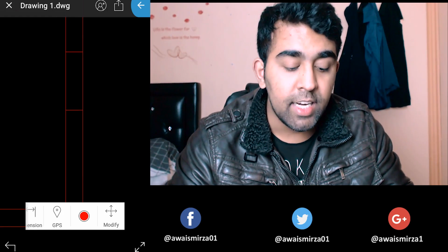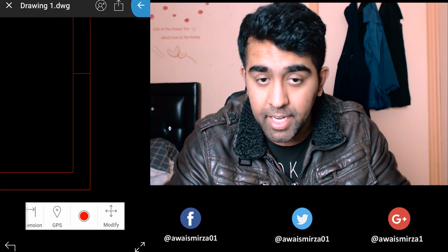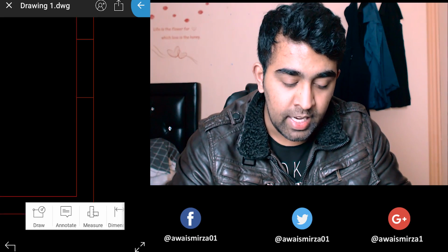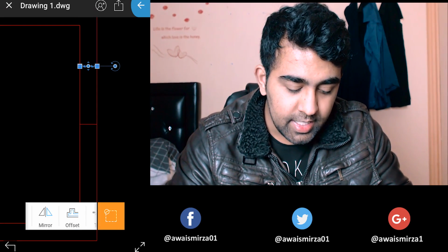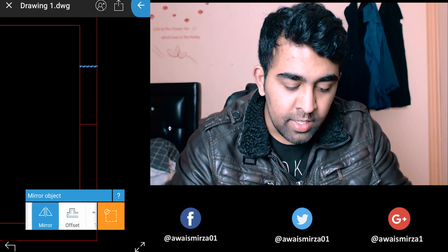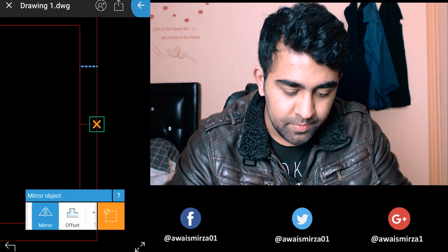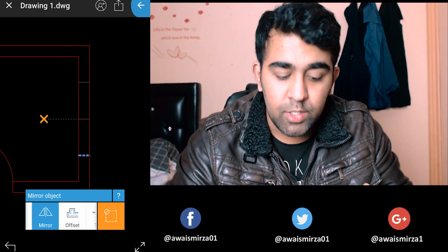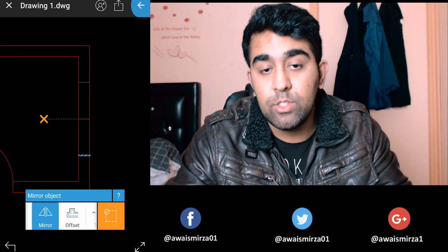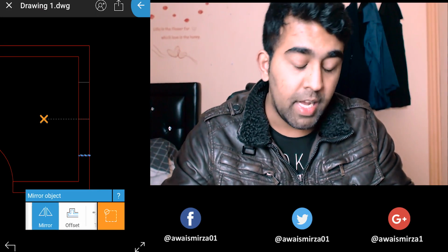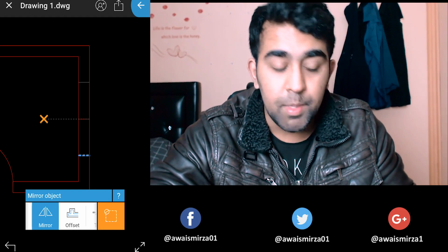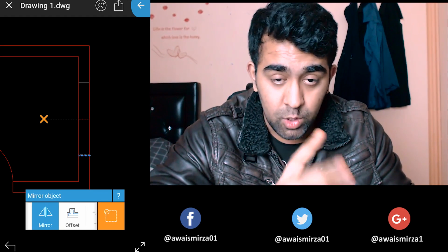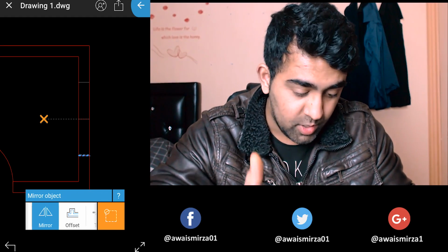Well, I can make another offset here, down here, to make that in the middle, but I want to show you the mirror command as well. So we're gonna go and select this line, tap on the mirror command, and now I'm going to select this point, okay, and then I'm going to select that point there. So what I did, if you guys know about AutoCAD, how to work with the mirror command, so select the object, select the mirror command, and then you select the midpoint. So you gotta make the midpoint. So I had that midpoint, so that's why.